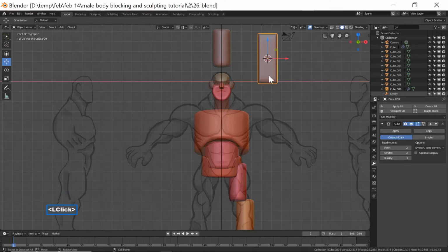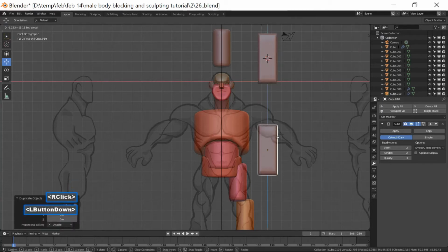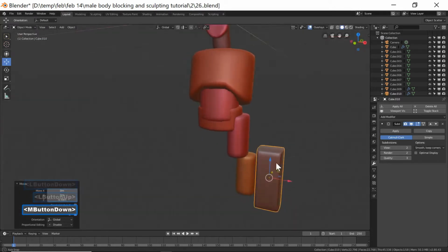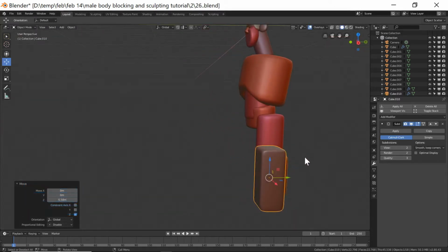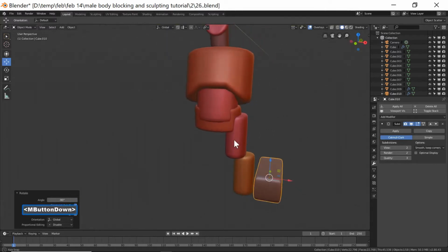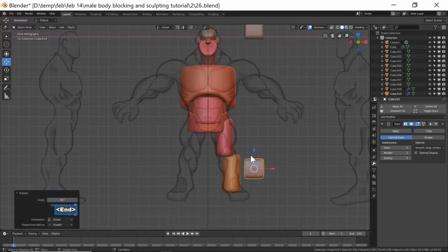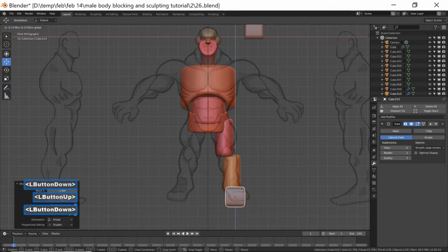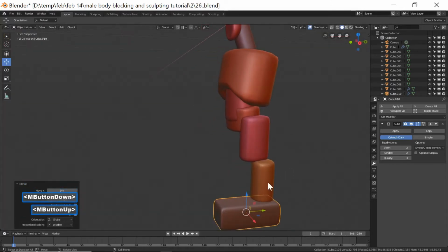Okay, I did that because I wanted a more squarish shape. I'm going to hold Shift, press D. And my thinking in this is, when you are just holding the middle mouse button to rotate, I'm going to press R to rotate on the X-axis, -90, and then left click to lock that in. When you're sculpting, sometimes things can get more round than you want them to. I'm going to press 1, go back to front view. So I wanted something that was more squarish to kind of help me go against that.